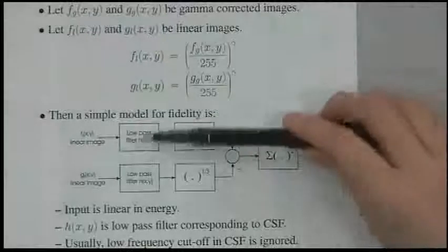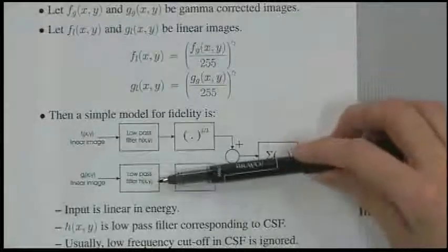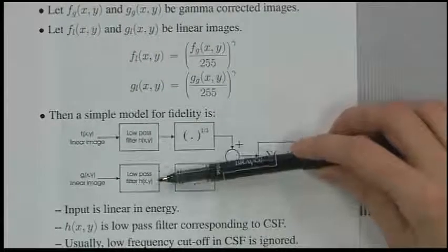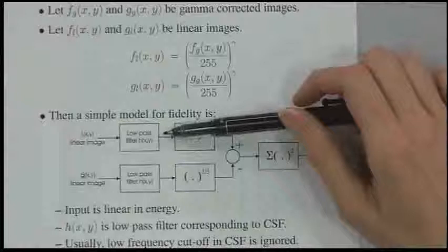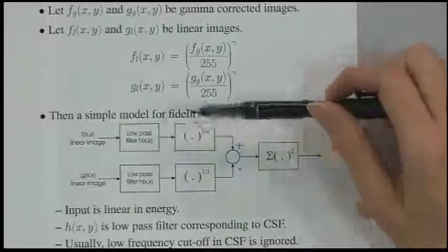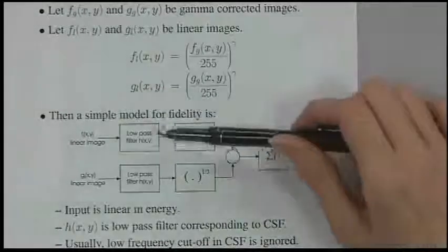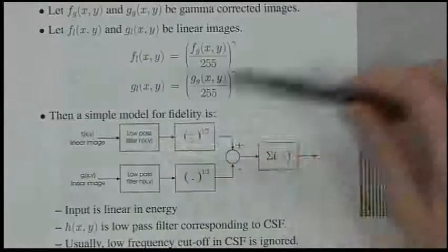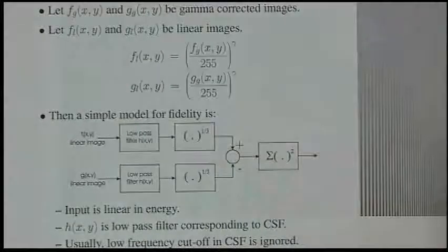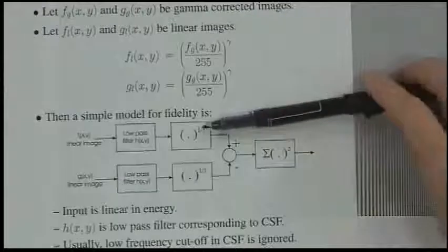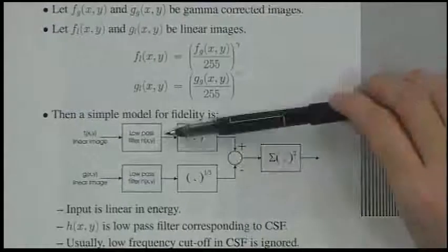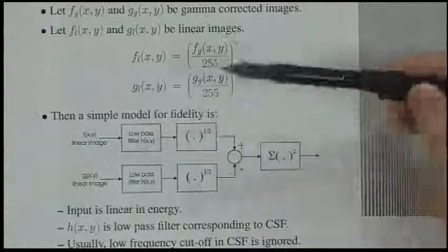But these filters are approximating the response of the human visual system. It's a low-pass filter that is modeling that response. So there's a strong assumption being made that the human visual system behaves as a linear time invariant system. But while it's a pretty strong assumption, it's not necessarily a bad one.